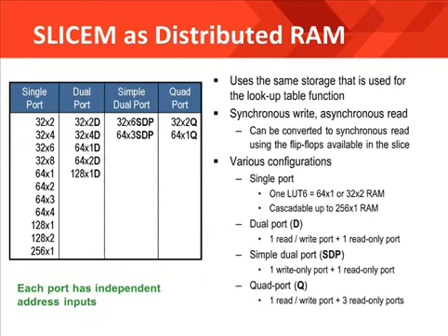Most customers use these resources for DSP applications. Sometimes customers try to build larger memories out of these. It is possible, but the extra logic to connect these small distributed memories together makes their performance prohibitive. So you may want to consider building a larger memory using the dedicated block RAM resources. In general, those customers that build with this are using the core generator or the system generator to build their DSP application.